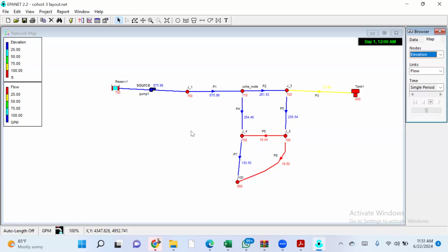But as a modeler, as an engineer, you need to troubleshoot your water system over a period of time. Like if you are drilling a borehole, we usually recommend 24 hours of pumping testing. If the aquifer can pump water for 24 hours non-stop, based on a calibrated discharge, you calibrate the discharge to be equal to the recharge. So as the well is recharging, you are discharging. If that well can run for 24 hours, then that well will never fail. That is what we call pumping testing.